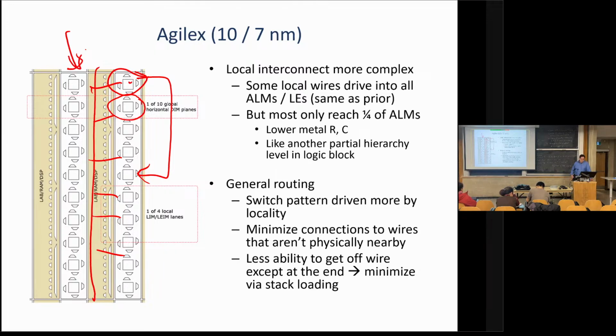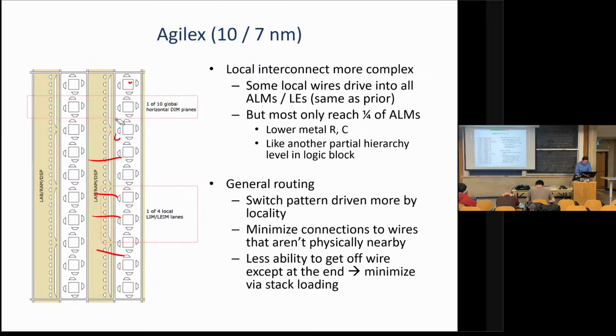But my guess, and it's a pretty educated guess, would be that because of those reasons, they decided they don't want to get rid of all the long wires. They still work. They're slower than the short ones, but they're still not that slow. So let's keep some of them because we still need that. If you didn't do that, you'd have to give these short wires the ability to drive each other, and you'd essentially start building a small island-style FPGA inside your island-style FPGA.